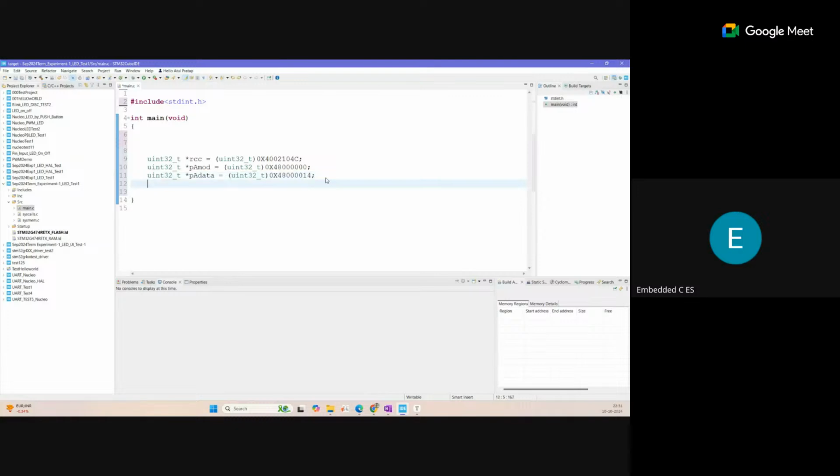Okay, after that, what we actually did is we set this RCC first bit. So we perform the OR operation. That OR operation is simply |= 1 left shift 0, or we can leave 1 also. So no problem, that is also fine. But otherwise, just make a practice of using left shift and right shift to perform things. So this enables the GPIO port A.